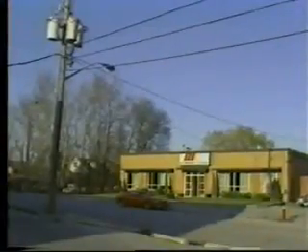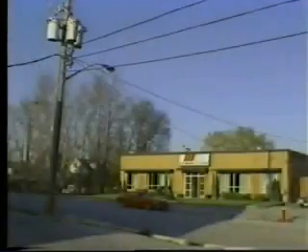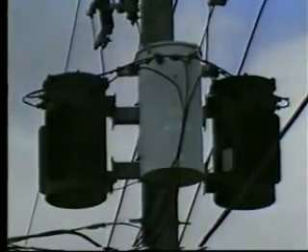For overhead applications, 3-phase transformer banks are usually made up of 3 single-phase transformers connected together. This allows the separate transformers to be equally spaced on the pole, thus distributing the total weight of the 3-phase bank. Typically, 3-phase transformer banks have total ratings in the range of 15 kVA to 500 kVA.